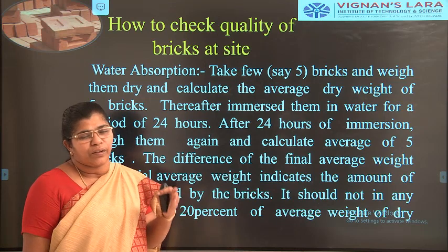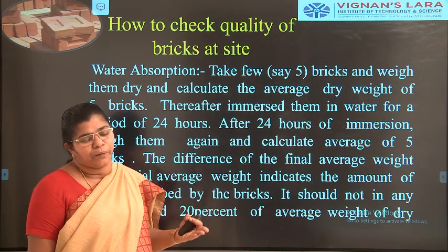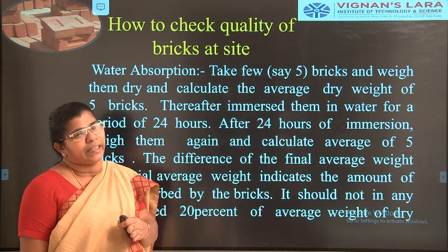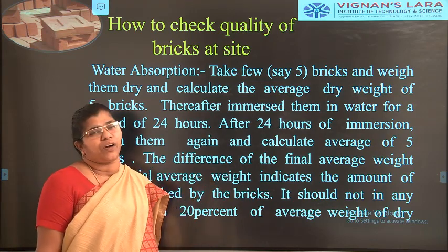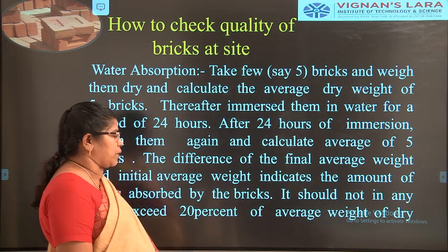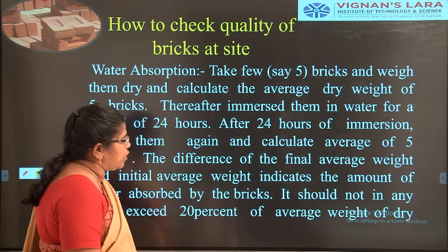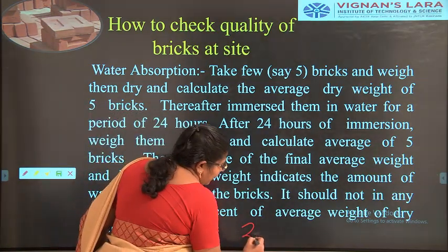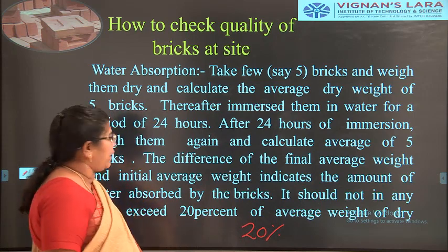The difference between these two weights is the water absorption. And the water absorption of very good bricks should not exceed 20%.